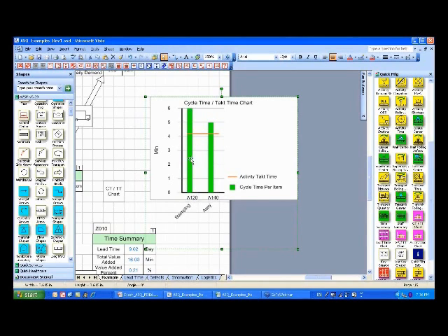But now the green bar shows the stamping can really only produce a part every 6 minutes. And assembly can only produce a part every 5. So here, what's going to happen is we're not going to be able to meet customer demand. And as you have bottlenecks like this, you get huge queue buildup in front of stamping and assembly.